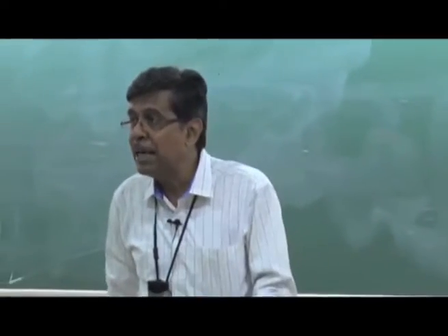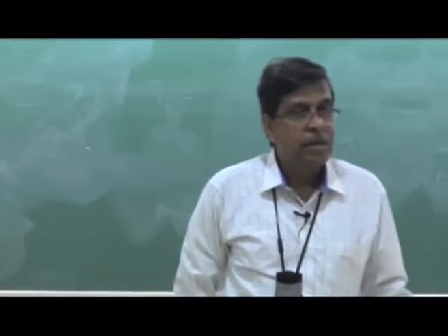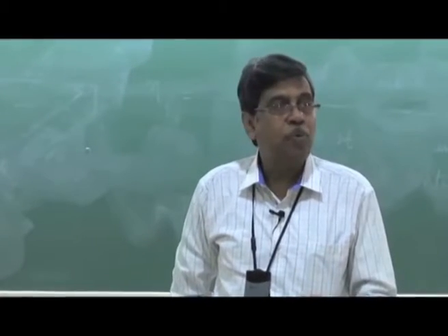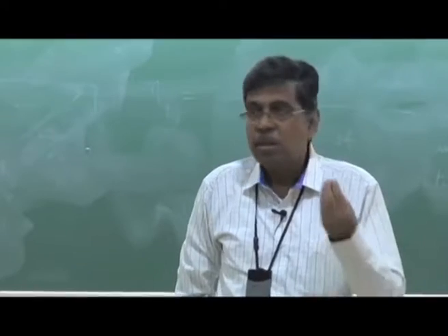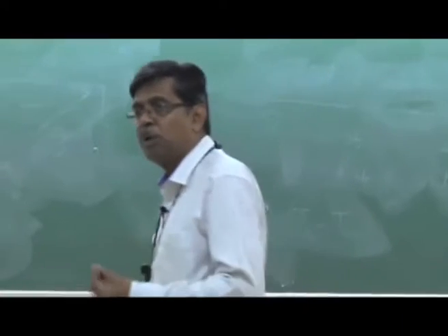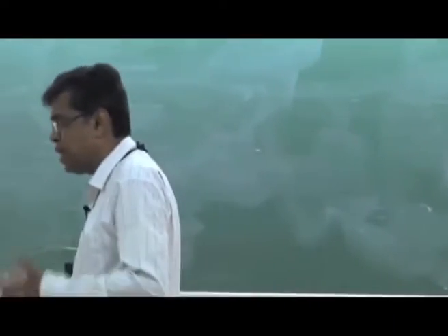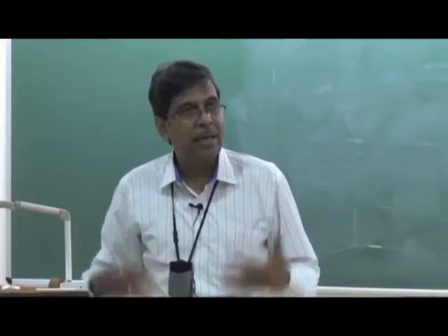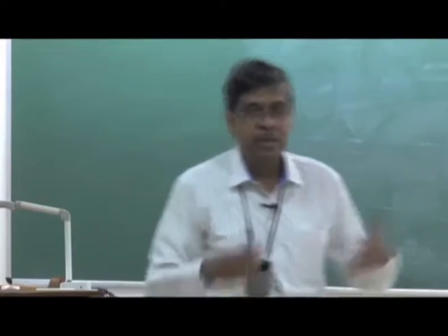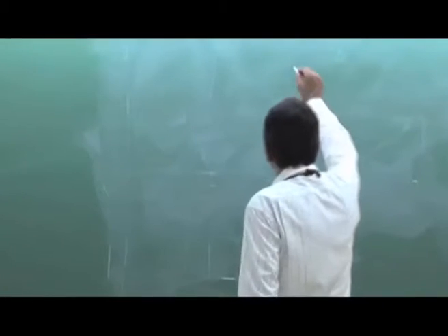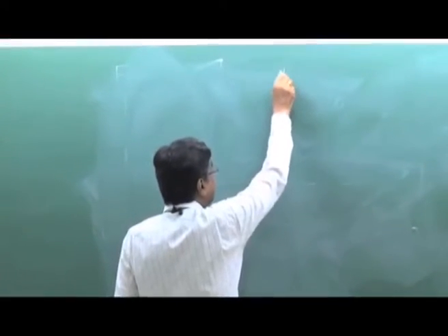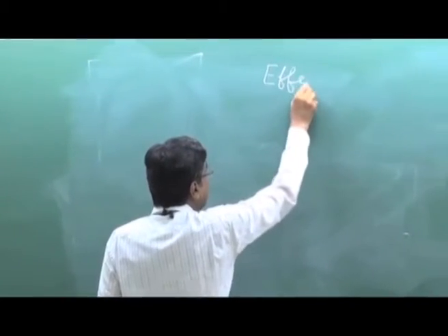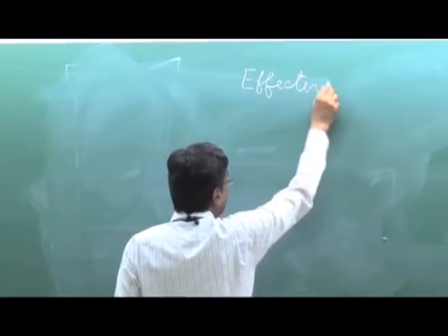If we have only a marginal gain in enhancing the heat transfer, then the cost will not be justified. You cannot judge from the economic point of view, because you have to purchase fins, go for manufacturing, attach the fin surfaces, and the entire fin system has to be fabricated. Therefore a question comes: the effectiveness of the fin, to judge whether it is effective to use fins.